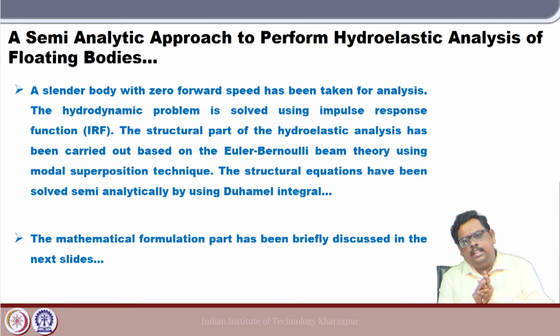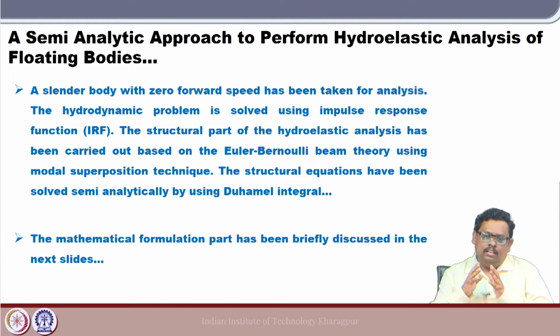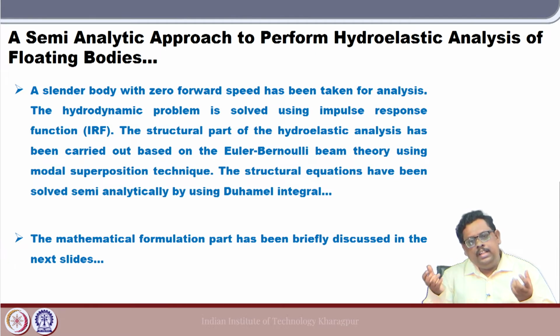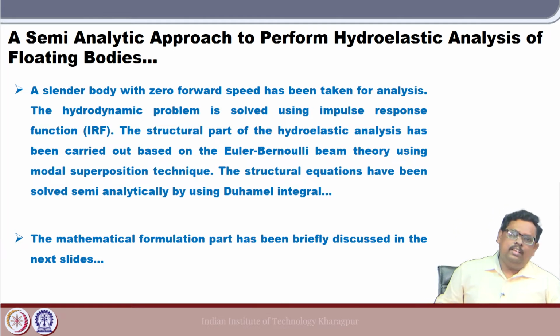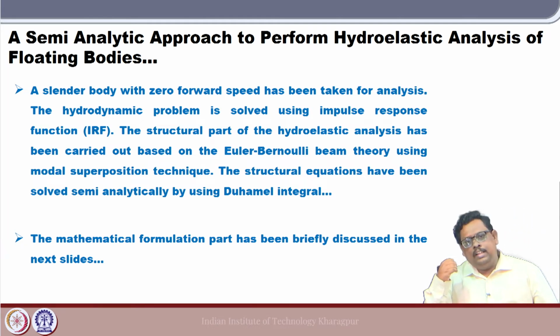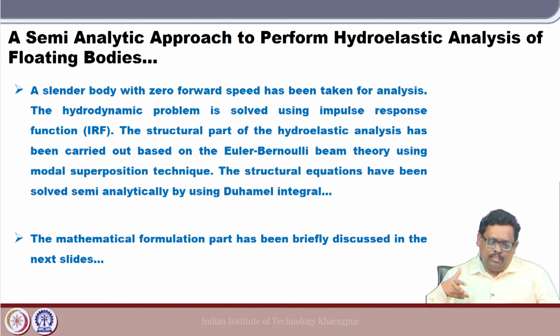We have already discussed the impulse response based method initially. So again we are using the same technique to find out the sectional force, and then we are going to use a modal superposition technique to find out the structural deflection, to convert the PDE, that is the partial differential equation, into an ordinary differential equation, and then we are going to solve it. Although we can call it a semi-analytic method, it still involves a lot of mathematics and some basic numerical techniques are still required to solve this problem.